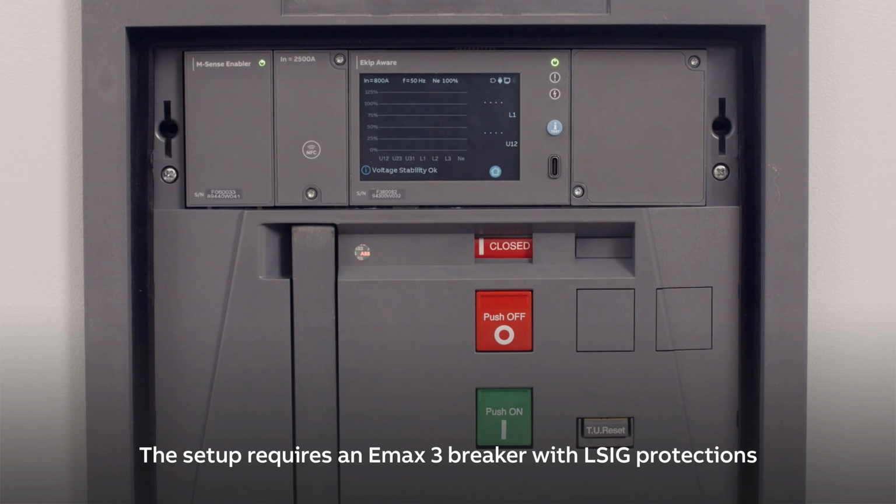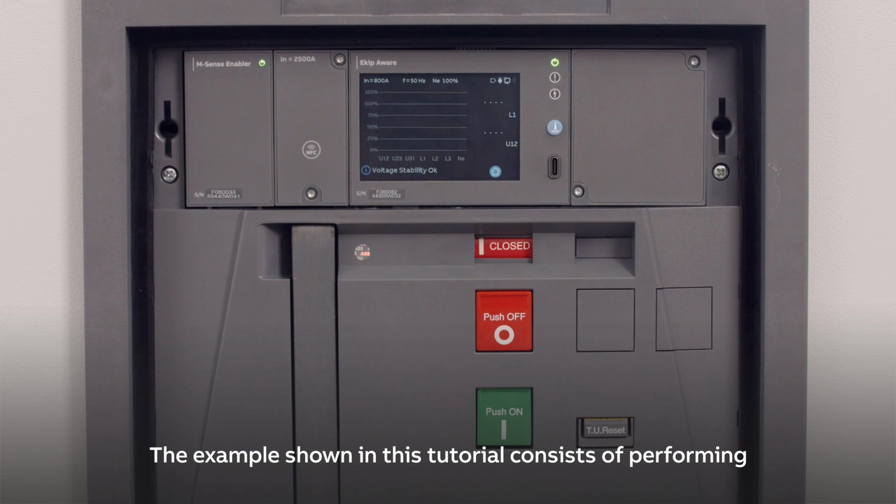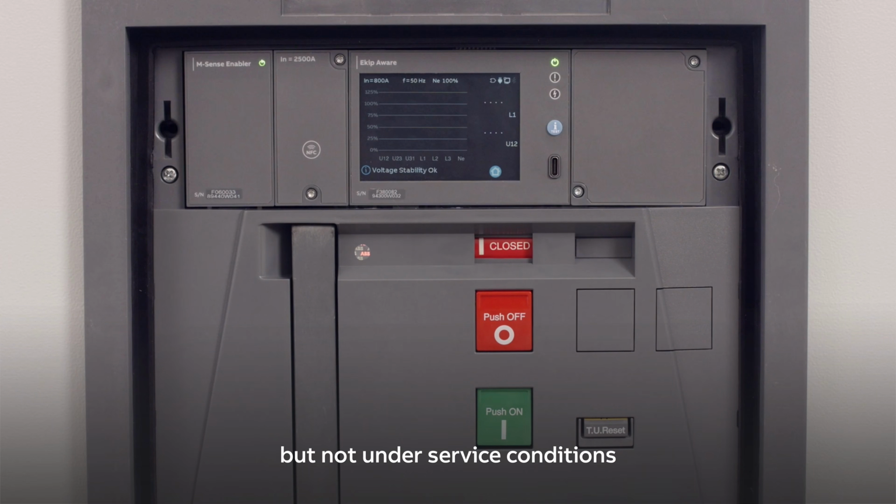The setup requires an Emax 3 breaker with LSIG protections and a digital upgrade necessary for Test Area Pro. The example shown in this tutorial consists of performing protection testing on the Emax 3 breaker with two powerful tools, LSIG Test and Test Area Pro. Make sure that the circuit breaker is closed, but not under service conditions before performing the tests.